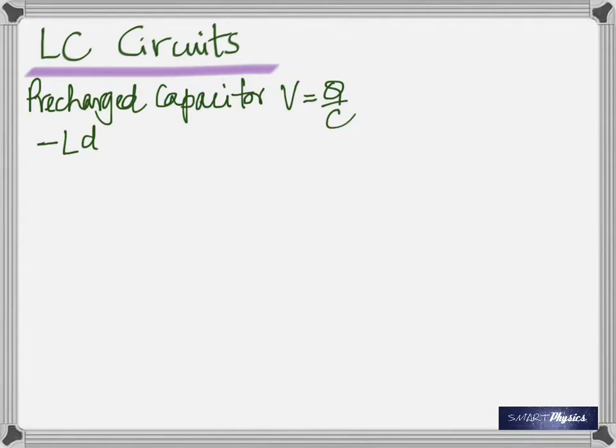And what's the voltage across the inductance? L di by dt. We wrote that just a few minutes back. L di by dt. Why the minus sign? Because it's a back EMF. Isn't it opposing? Okay. That's the math that's beginning now. That's Kirchhoff's voltage law just applied. There's more than what you see there.